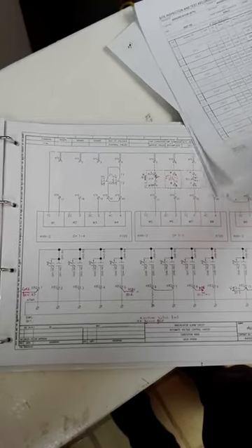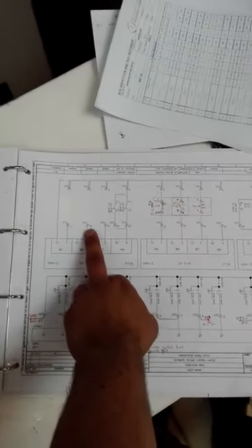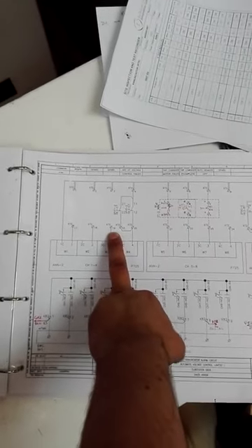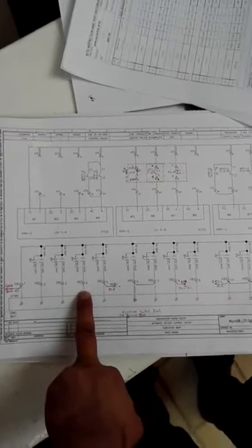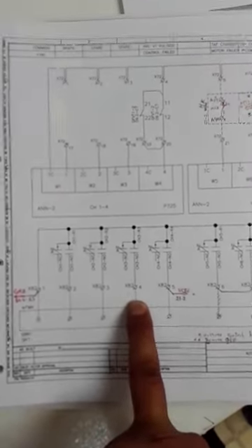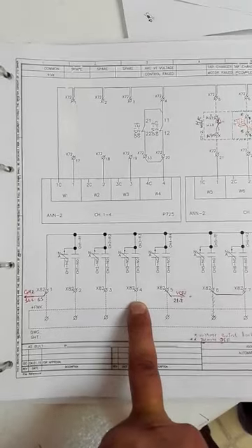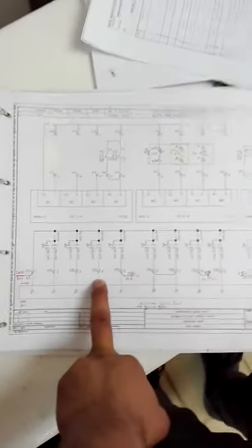So if you understand this pattern, we will follow the same pattern and just measure the time. Now we will move from point 18 to point 19 of our terminal block X72. Okay, and the same pattern will be followed. Here we will move to X82.4 and we will measure the time and the delay to come to its normal position.